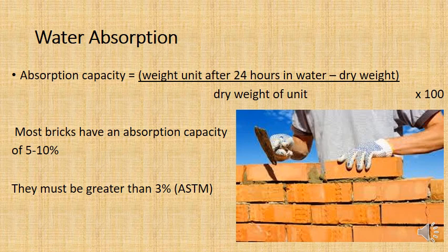You're seeing that happen with a lot of the bricks in the old bazaar area. Have you noticed how the bricks are not actually a nice smooth cuboid? They're basically breaking down into smaller and rounder shapes. That's because their absorption capacity was probably a bit high. It might have been as high as 15%, I think, for them. But yes, absorption capacity is a bad thing if it's too high. However, you can't have it too low. Why is that a problem?